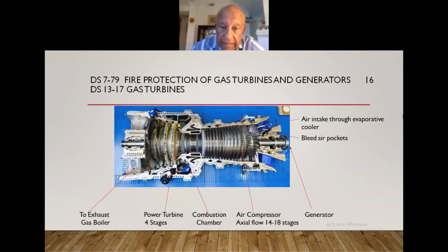So what happens is the excessive salt travels through the turbine and comes out of here. And you saw the ports on the blade that distribute the cold air to the blades; the salt chokes up those cold air passages. So the blades overheat and fail.